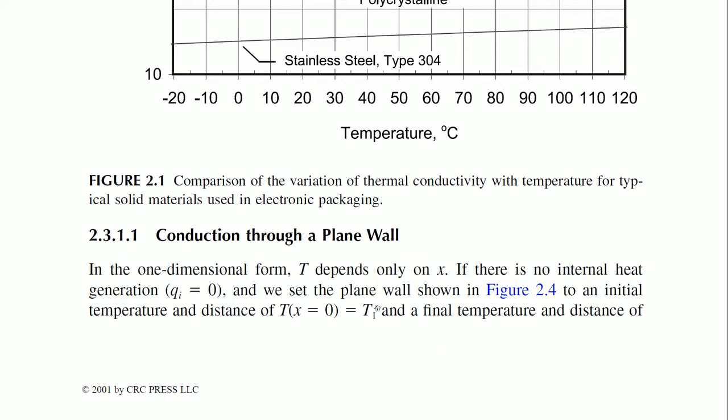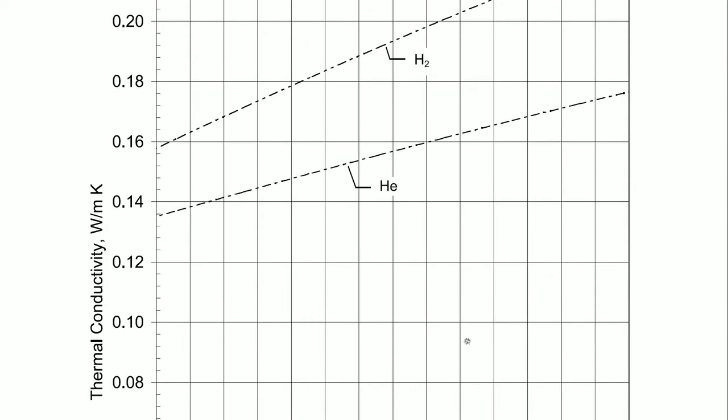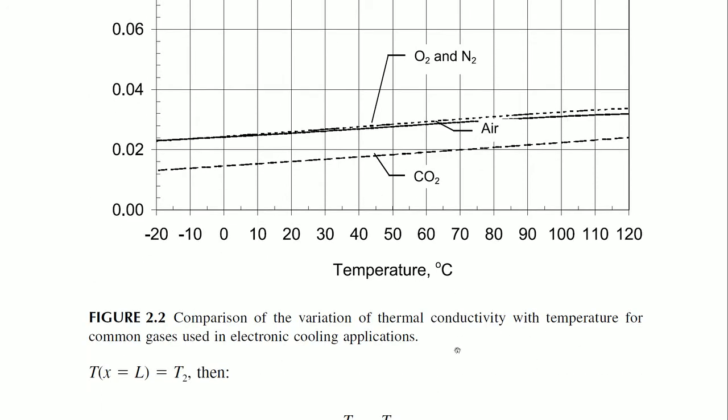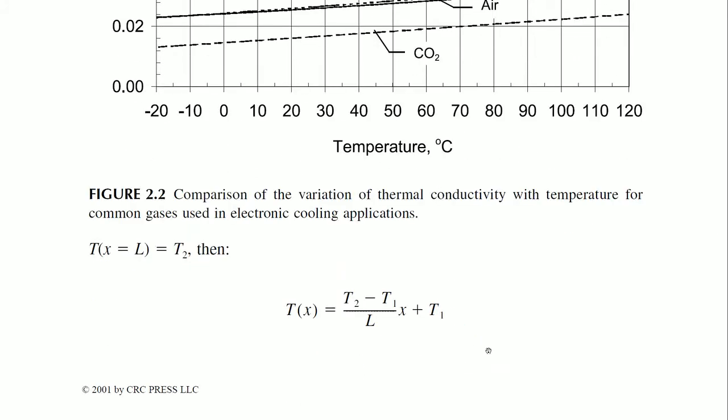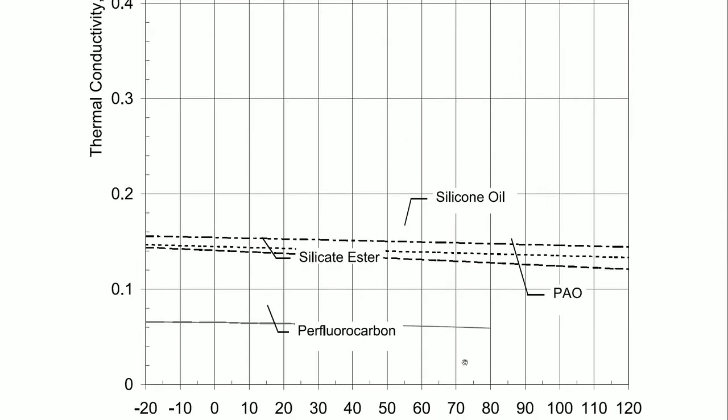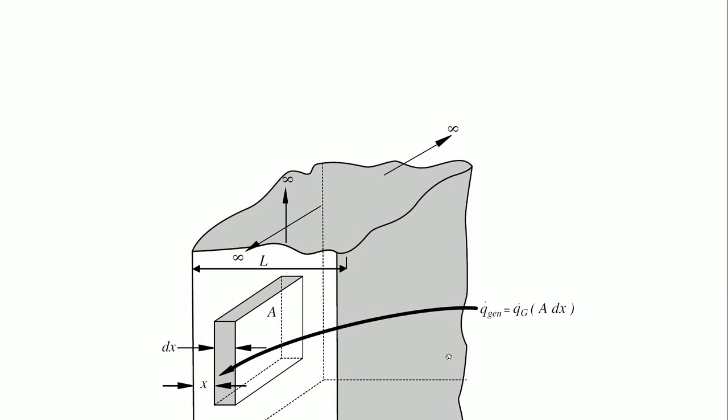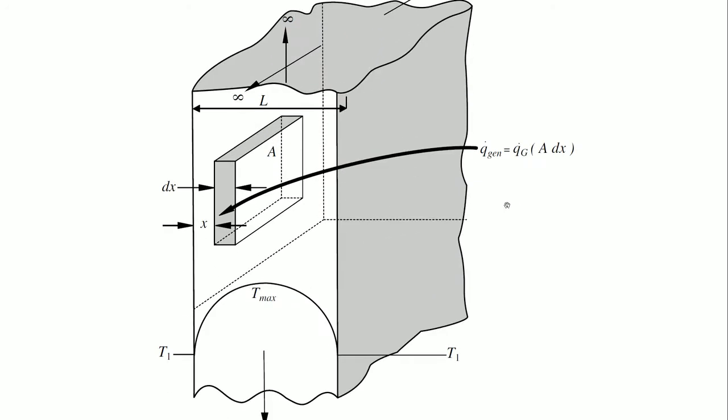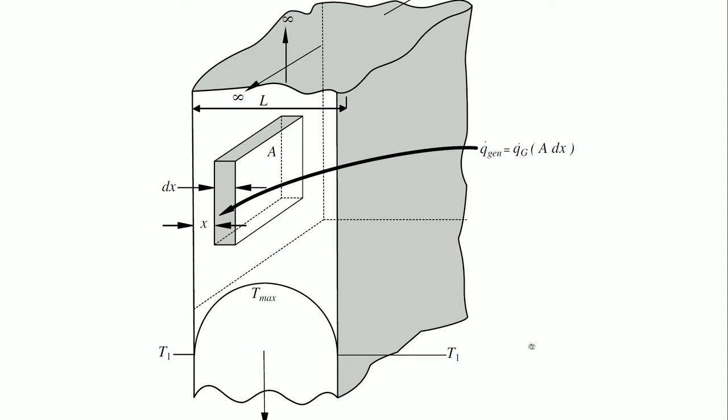Now, we come to these interesting things. The succeeding chapters give you things related to this analytical part of it, saying we have an area, then we have how heat is conducted from here, from there how this is taken out, and I have shown you a practical example of a heat sink on which a TO 220 package is mounted, and this is typically the total area that is covered.